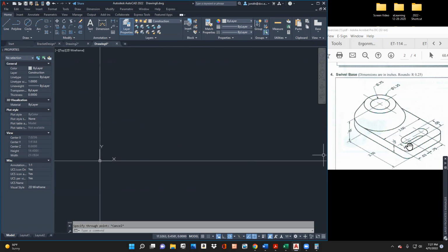In these kinds of activities, we want to make this the top, and that's pretty obvious. But typically the object with the most mass is going to be the front, so I'm going to make this the front view here. Knowing that the overall width of this is 2.5 plus 1, the radius, I would say offset, and the distance is going to be 3.5.